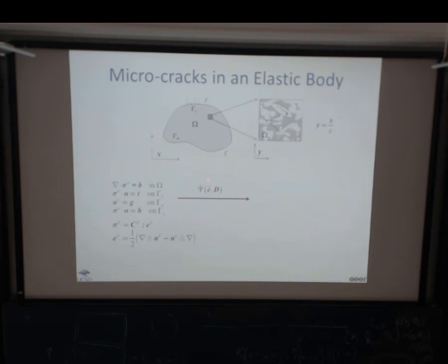I'll use the history of free energy with respect to the homogenized strain and extract some damage law out of it. Okay, so that's the rationale here. So hopefully through this process, I'll be able to solve the problem at the upper scale. The stress and strain relationship are then constructed from this Helmholtz free energy. Okay, so this will be the key of this whole process. As long as I can obtain this, then I can solve this elasticity equilibrium equation with damage law at the upper scale.